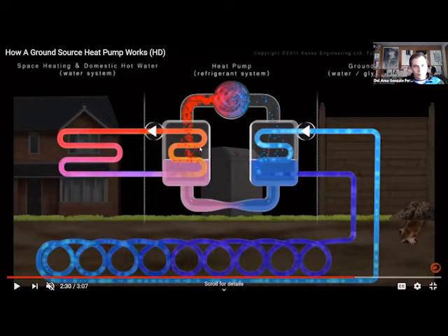We explained what a split system was, but in the split system, one of the components is the evaporator and the other one is the condenser. And the compressor and the expansion valve, they are somewhere. It can be either close to the evaporator or close to the condenser. But a split system, it's a heat pump in which we have these two components in different places. In other heat pumps, we have these two components in the same box.